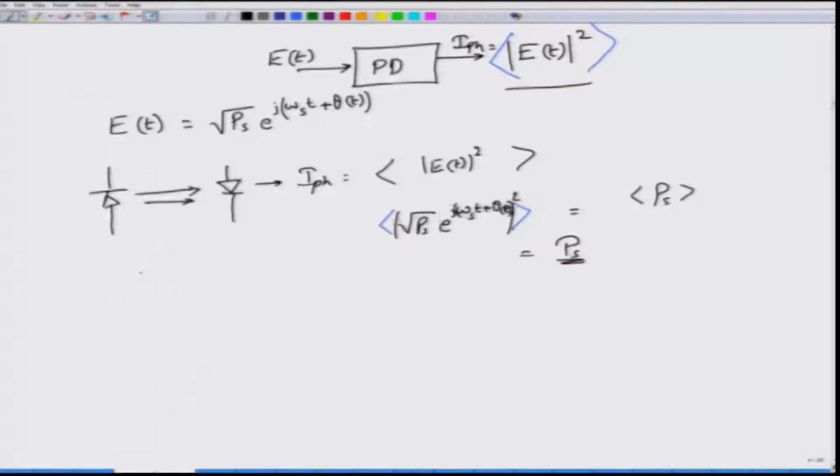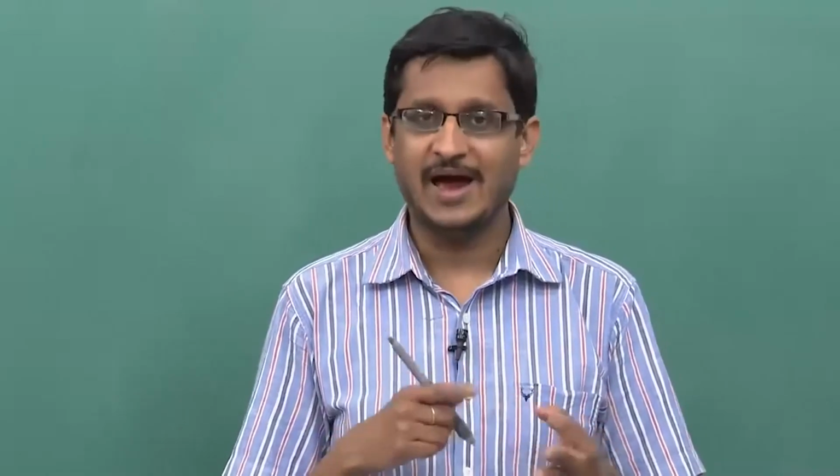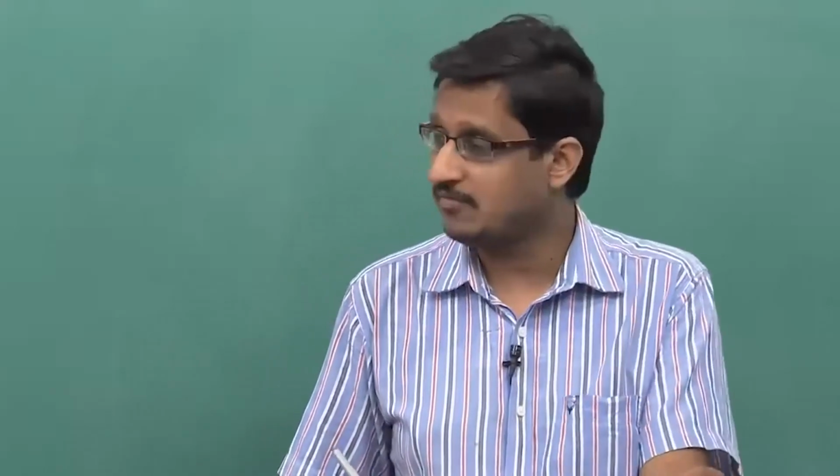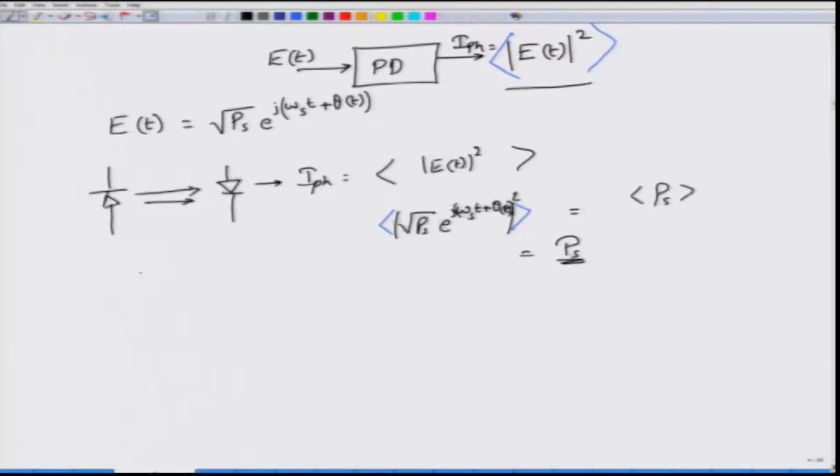So although this is titled as optical receivers, we are really looking at the detection mechanisms. A full receiver will consist of a biasing circuit, it will also consist of some low noise amplifier, also sometimes called a preamplifier, and then you will have a main amplifier, some additional filtering circuits, and some detection, synchronization and timing circuits.